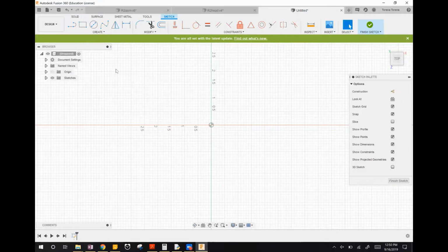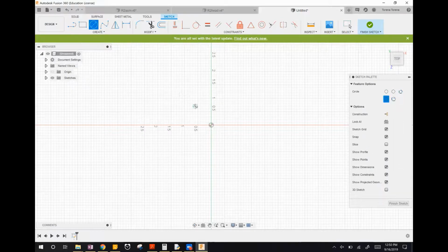Now, you're going to want to add a circle by clicking Center Diameter Circle. The first point you click on will be the center of your circle, and the second point will define the diameter. As you can see right now, it's going to select the diameter based on where I put the second point. Now, as you'll notice, the circle is currently blue. In general, in sketches, when things are blue, that means they're not well defined. That is, later on in the assembly, it'll be possible to drag these around and change them. Usually, it's good practice to keep everything as well defined as possible.